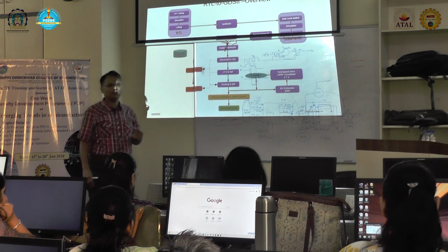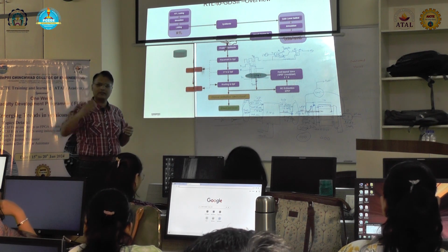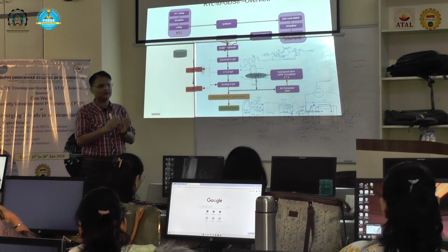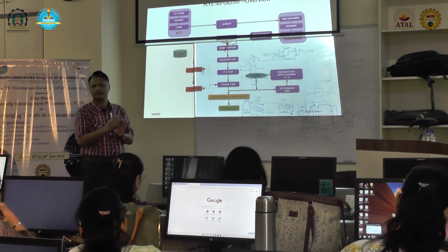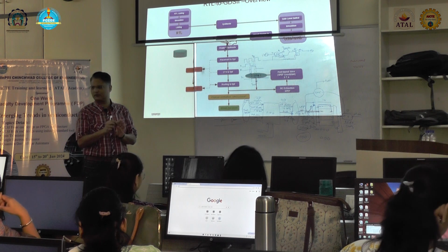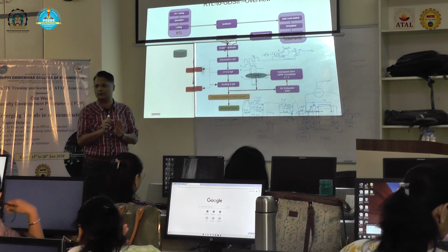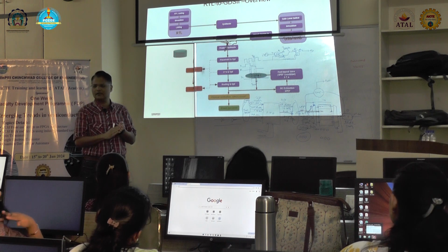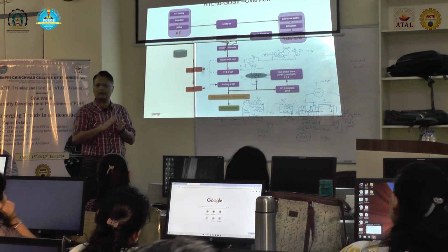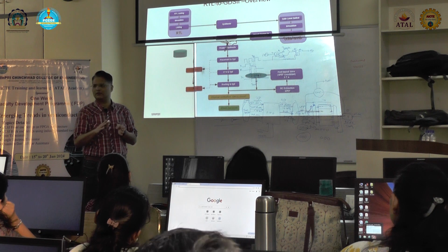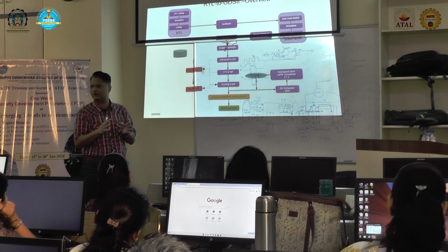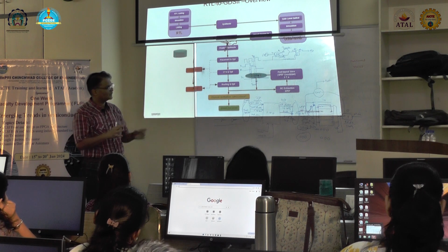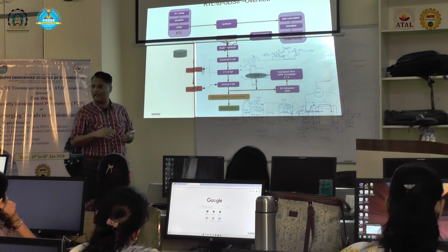DRC is nothing but design rule check. It will give you certain design rules, such as that between two transistors you should have at a minimum this much gap. Okay. So you should have this distance minimum. If you violate that DRC, this chip is not production worthy. Okay. You cannot take it out with that. It will not function correctly. So that is design rule checks.